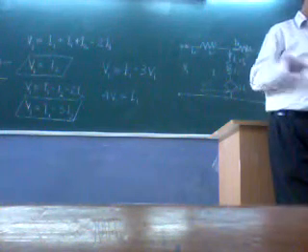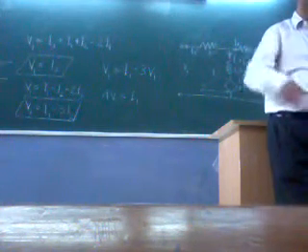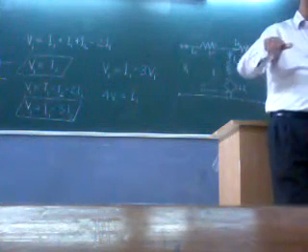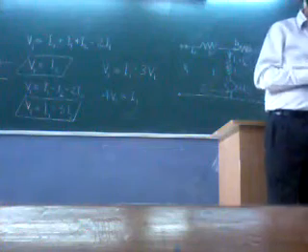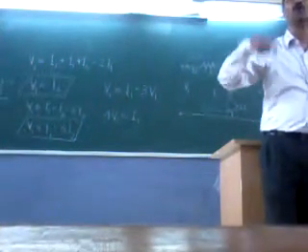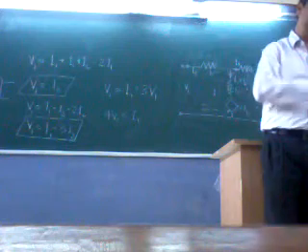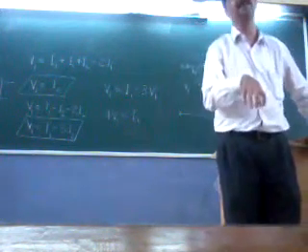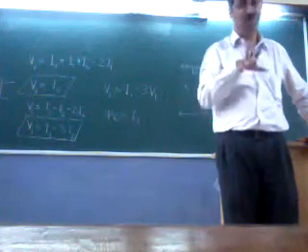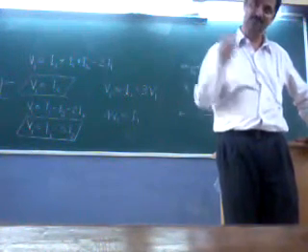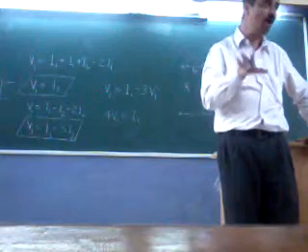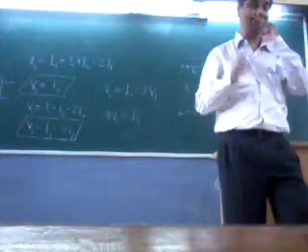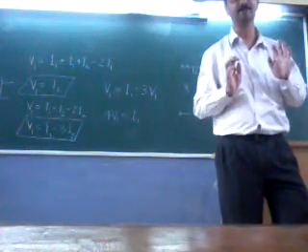Or we can express the same by Y parameters. For that we have to short either one of the ports. The same we can express by H parameters. For H parameters, one port you have to short, one port you have to keep open. Or ABCD parameters, again the same thing is there. So that set, the Z parameters, Z11, Z12, Z21, Z22, or Y or H or ABCD, is one form of explaining the network completely.